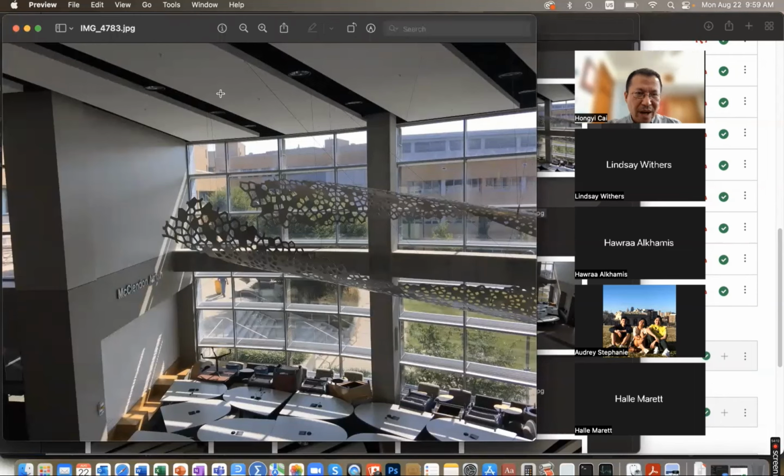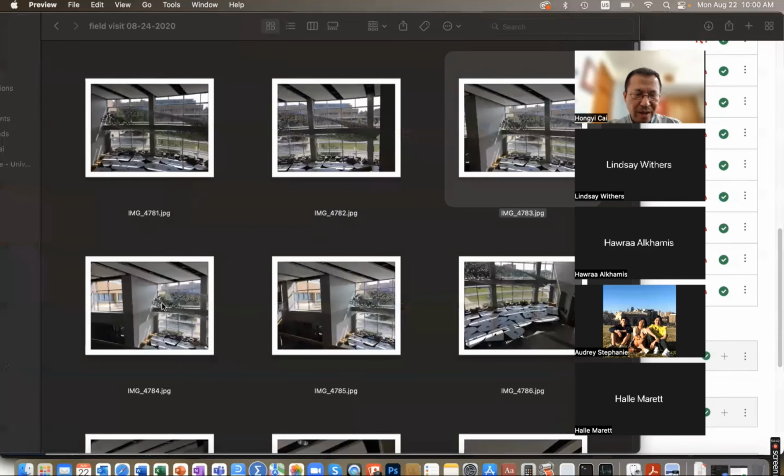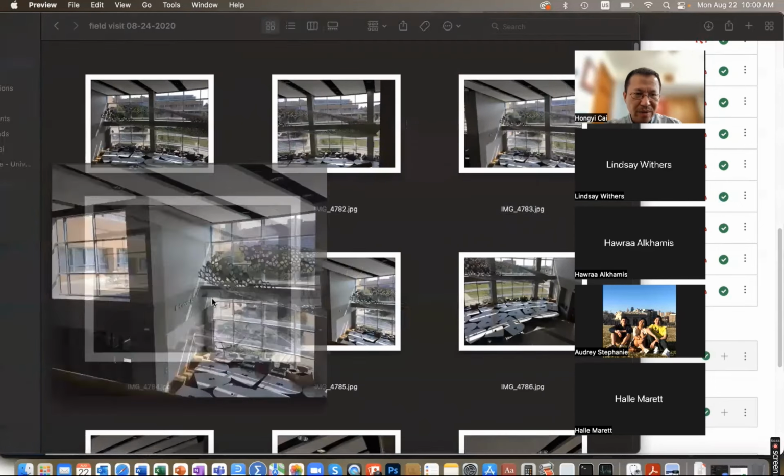When you have a higher sun, like in late morning, the sunlight will have an angle different from the morning, because if the sun is just coming above the roof over there, you will have sunlight penetrating this way, so the angle will be different. This angle is called the profile angle. I will talk about this later when we talk about daylighting knowledge in chapter 2.